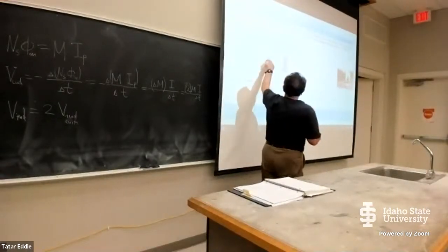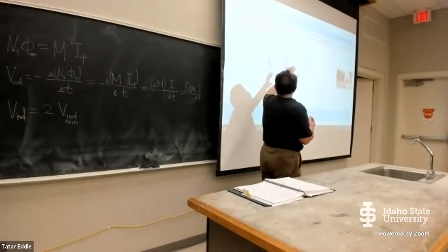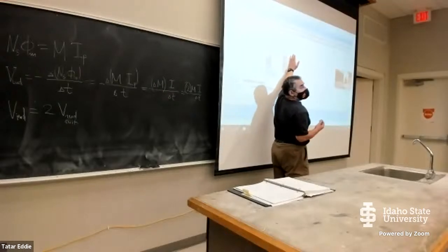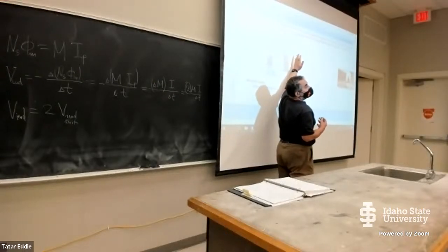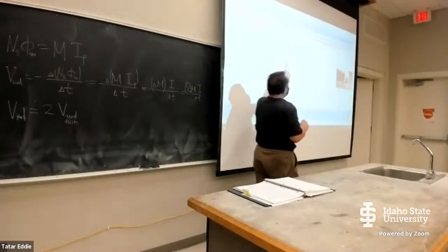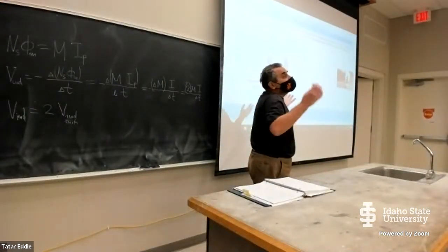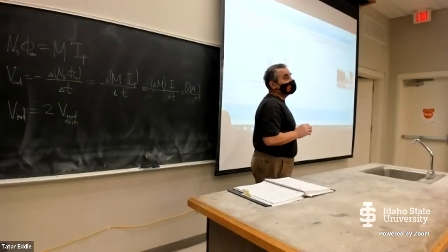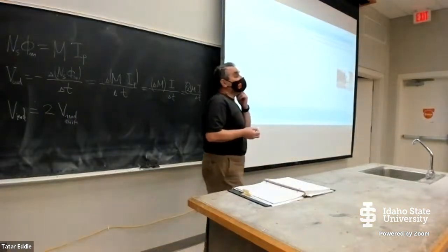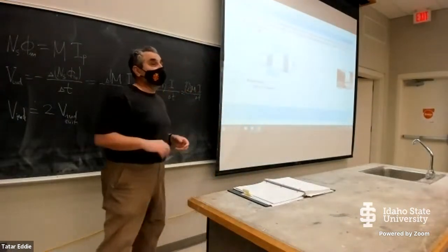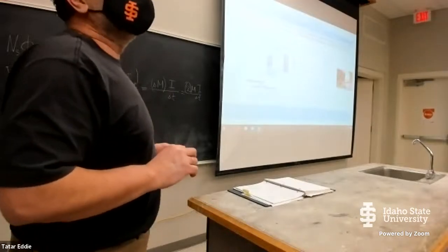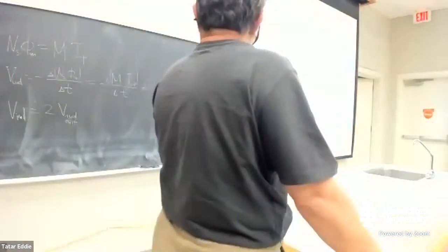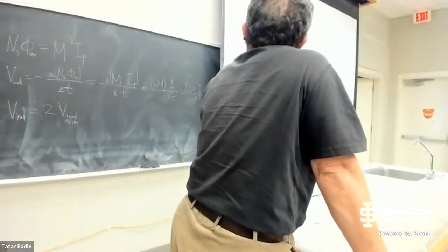And this iron core makes sure that all the magnetic flux that is generated in the primary is moved to the secondary coil practically with almost no losses. Just the ferromagnetic materials attract those magnetic field lines, and almost no magnetic field lines go outside. So you have a transformer with 2 coils, of course.